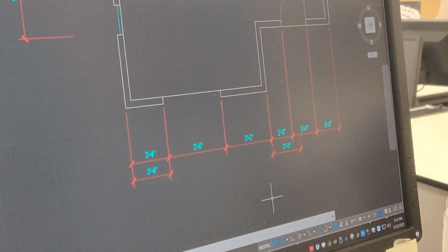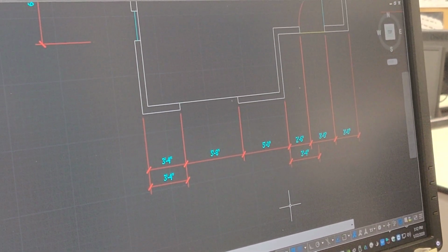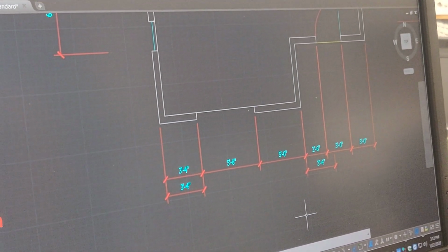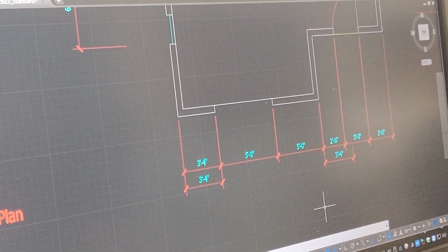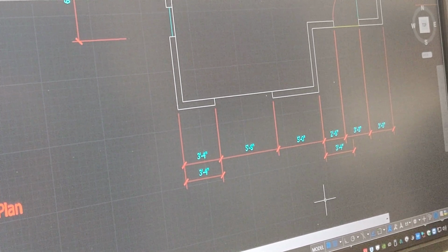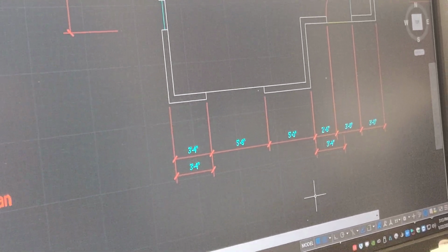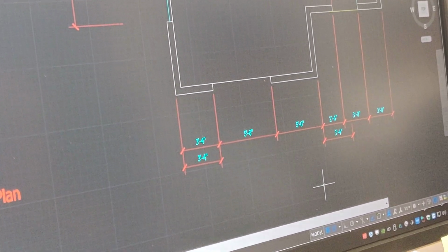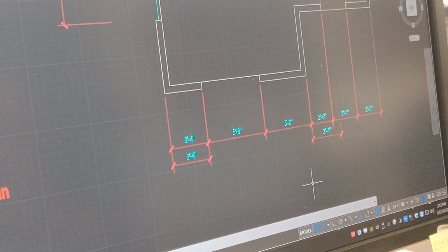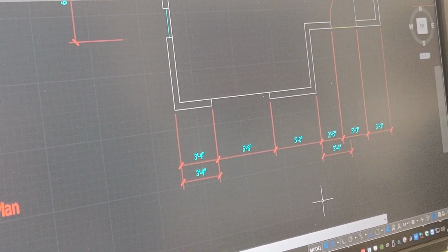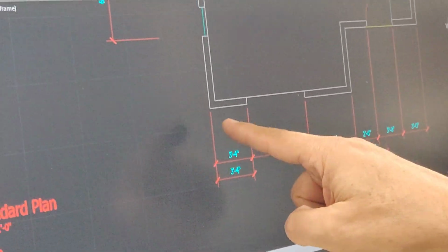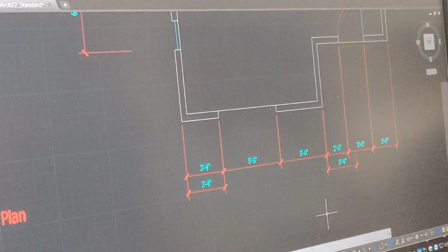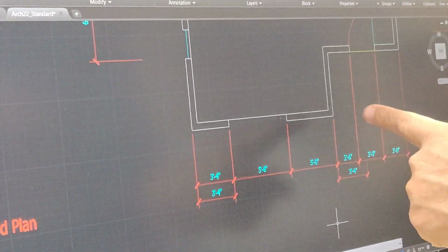When you're laying stuff out, do you lay out to the center walls? When you snap a chalk line on slab, what do you snap to? One side or another, right? Okay. So, contrary to what your book had in Architecture 12, when I teach my students dimensioning, you dimension to the face of framing. Because when they're building the walls, that's what you do, right? Well, in this case, we have outside the building, and this is outside facing the building too. So, we're naturally going to go that.